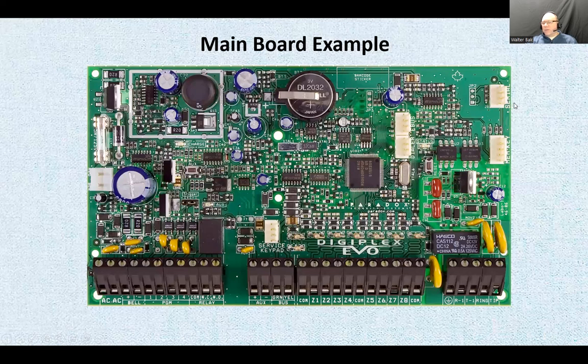Like, for example, if you want to use your laptop to program this system, your laptop serial interface will connect into this serial port, and then you would be able to communicate with this board and do the setup. And the setup would be setting up codes, setting up zones, setting up all kinds of things. Right.